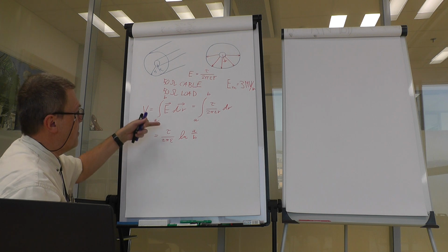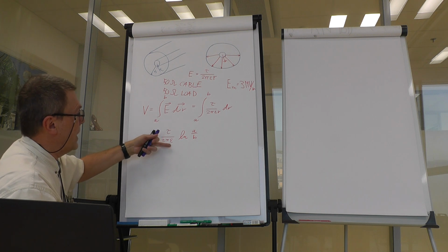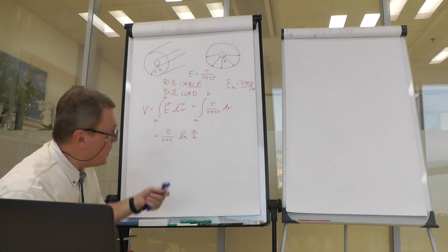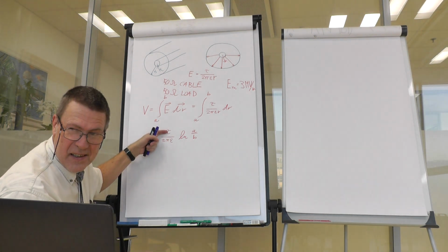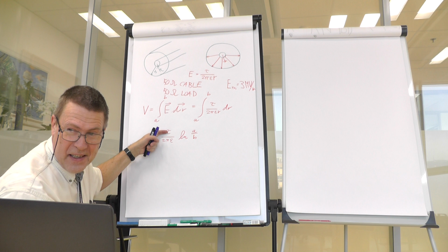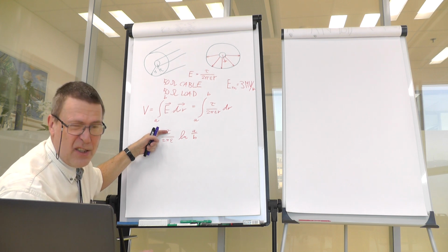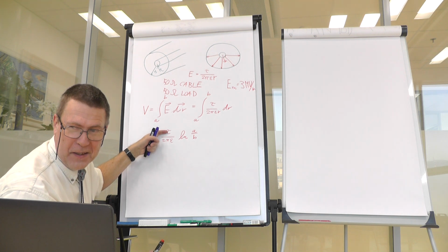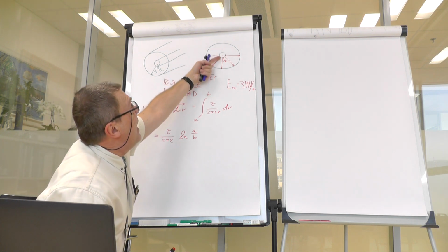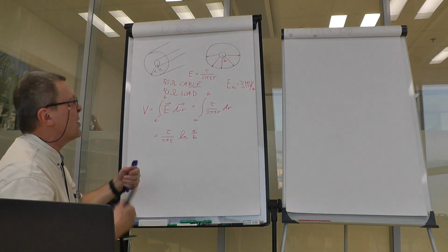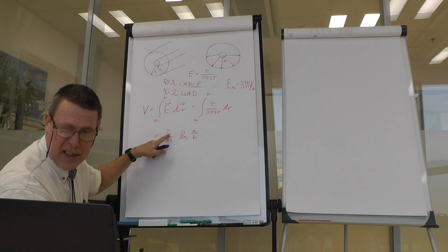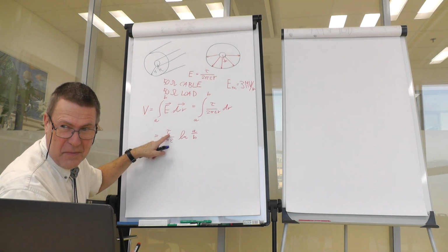So this is the voltage which is here. Now this is generally the voltage for some given charge density. We have not established the charge density for the case of maximum field at the surface of the inner conductor. So now we would have to find out this charge density that is critical.